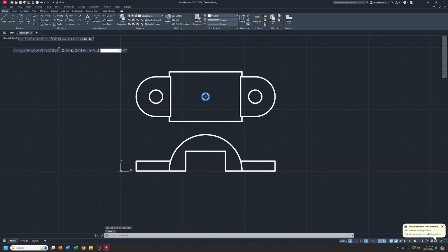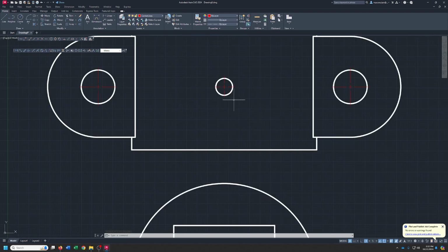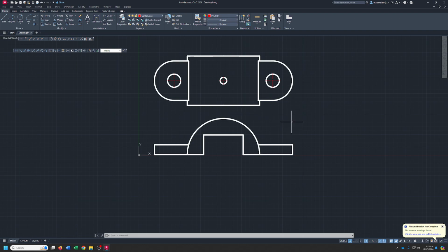I guess you gotta keep picking it. Center point. Center point. All right. Now, watch what happens when I try to do hidden lines. They're going to look solid. So how do I fix that? Once again, the good old LTS thing. So line, type, scale. Okay?